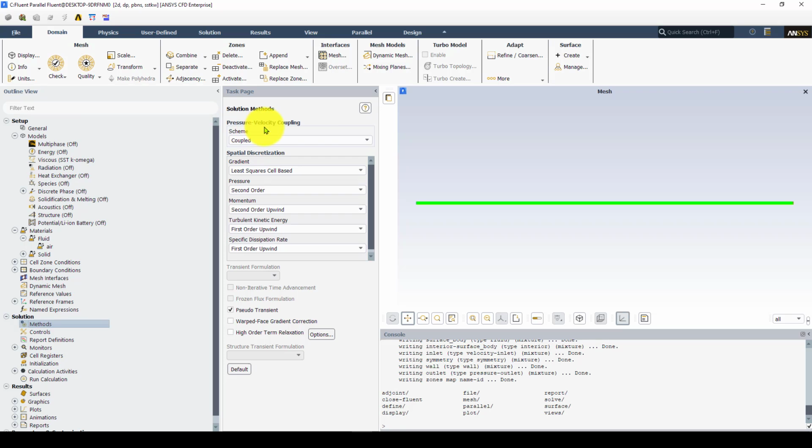Since you use this kind of coupled solver, the other option is the segregated solver. So all of the SIMPLE variants are segregated. Okay, they use less memory. So let's use, in this case, SIMPLE as a good option. Here the memory requirement is almost proportional. So 1 million cells, 1 gig of memory.